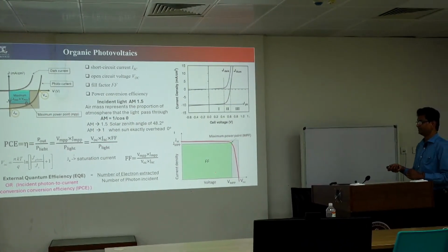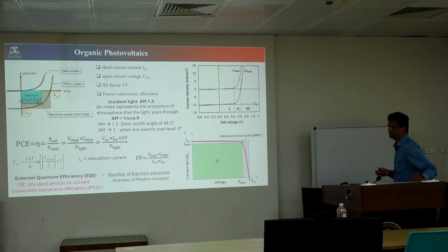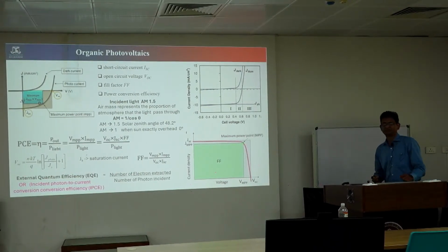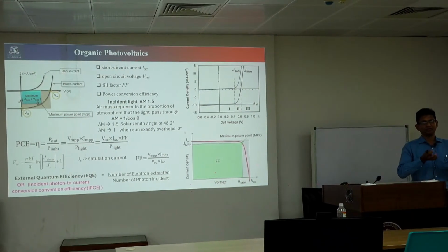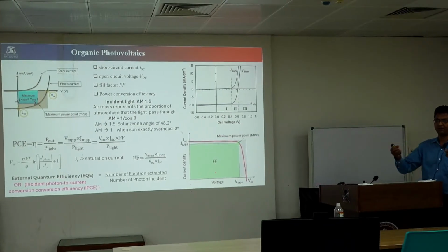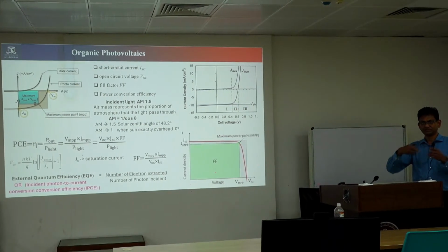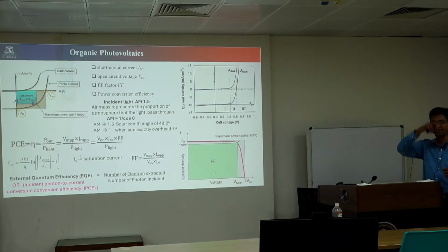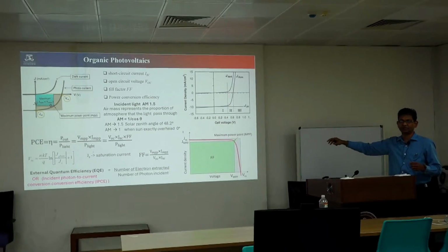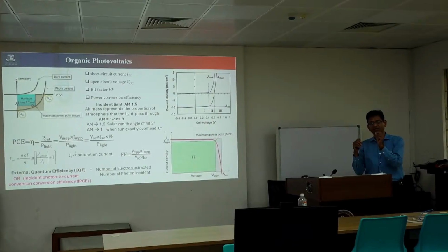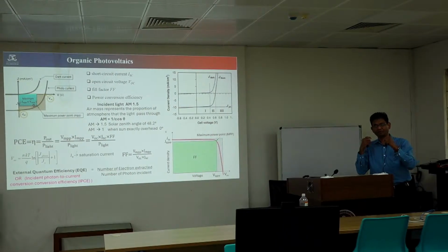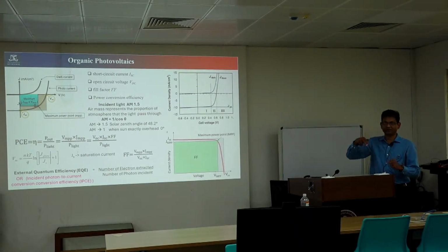Another factor is quantum efficiency. We have the solar spectrum from 300 up to about 1100 nm that we can measure. Not all wavelengths of light are the same. As I said previously, the light intensity varies with wavelength. Some wavelengths give a lot of power; the spectral rate is different.